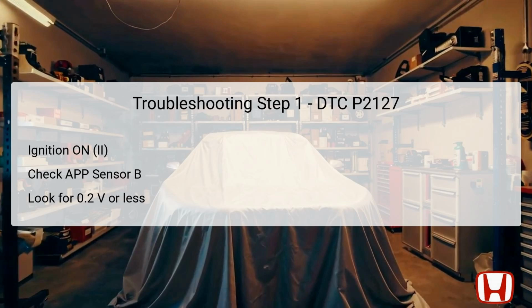However, if the voltage is above this threshold, it signifies an intermittent failure, or that the system may currently be operational. In this case, inspect for poor connections or loose terminals at both the APP sensor and the ECM before continuing with further tests.